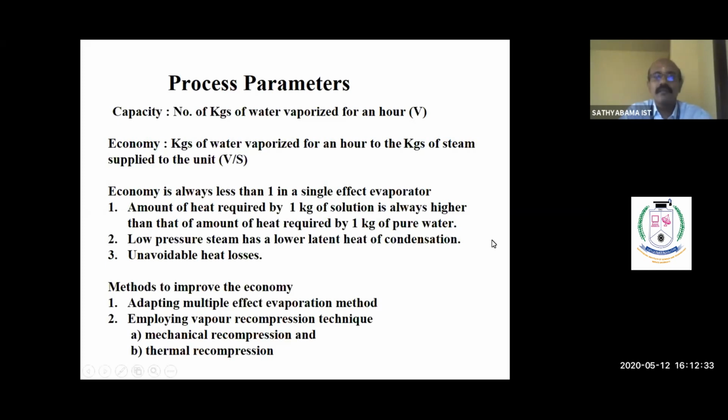The economy is always less than 1 in a single effect evaporator. There are certain reasons for that. Number one, the amount of heat that is required by 1 kg of solution is always higher than that required by 1 kg of pure water. For example, if 1 kg of pure water requires 0.8 kg of steam, whereas 1 kg of solution will require a greater amount of steam.